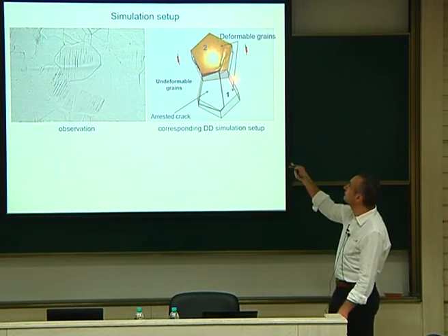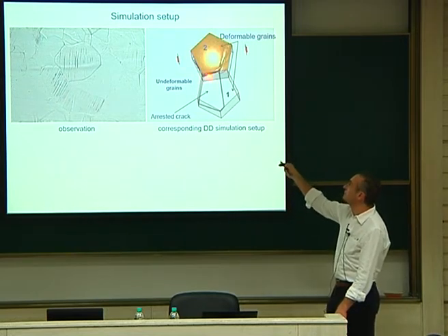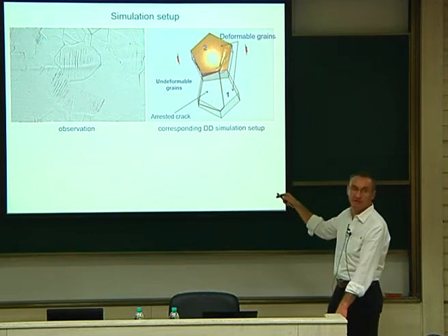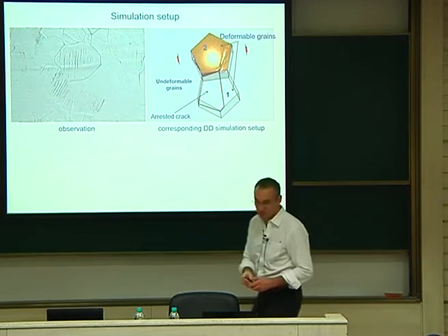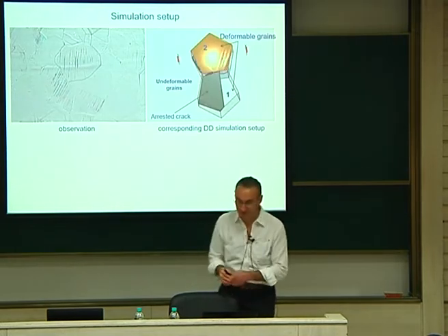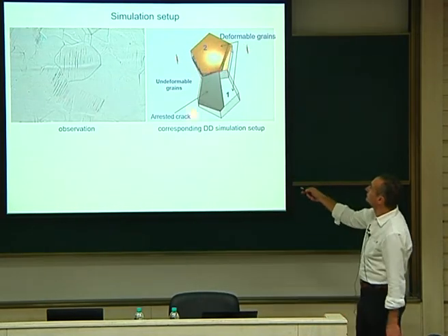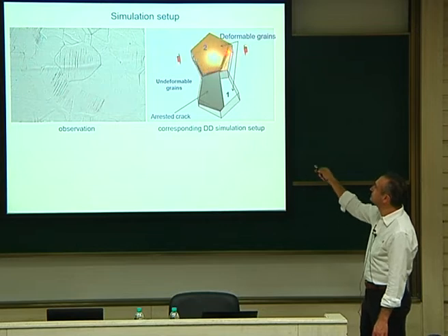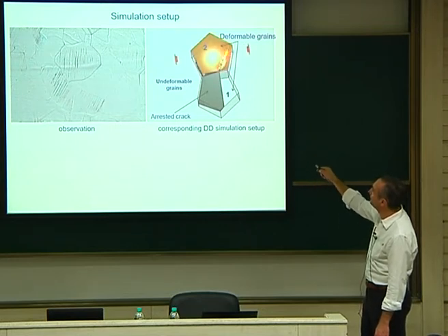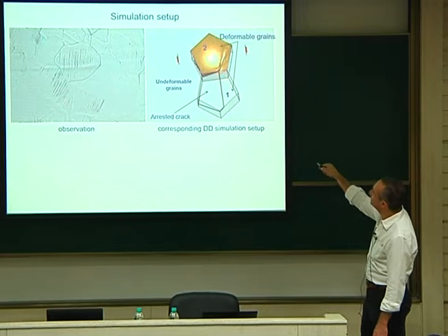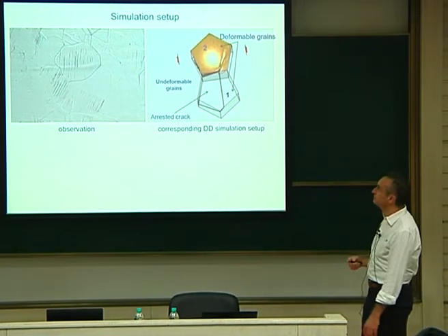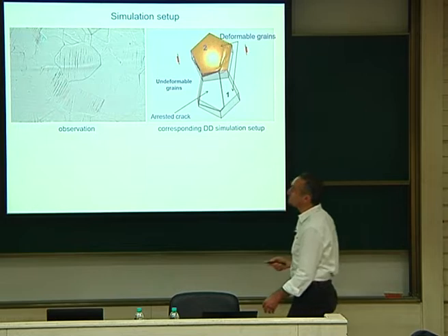So it means that we are dealing with that grain. This is the simulation box. And we assume that there is another grain here with a crack inside. So what we do, we can see the movie again. We load with no crack. The crack is not there. And then we put the crack, and we see what happens. So when we load without the crack, a persistent slip band will form. Here you see the band. And then when the crack is there, you will see if this changes or not the band which is developed in the next grain. Okay? So this is the idea.